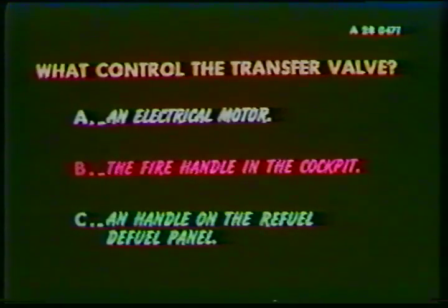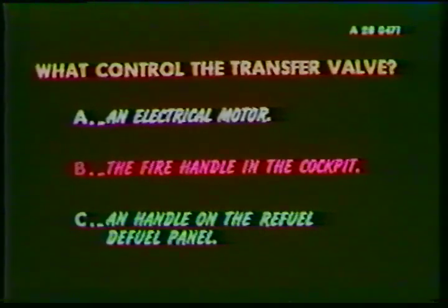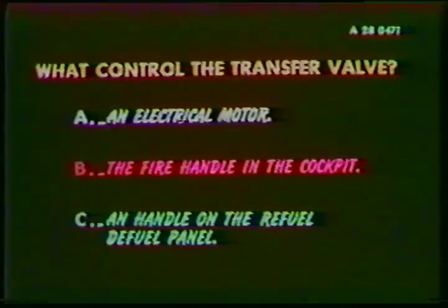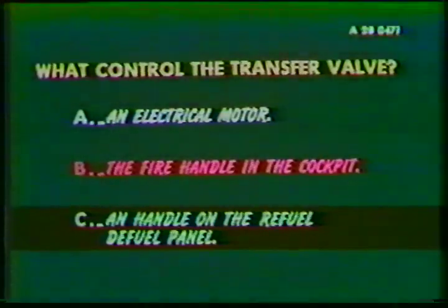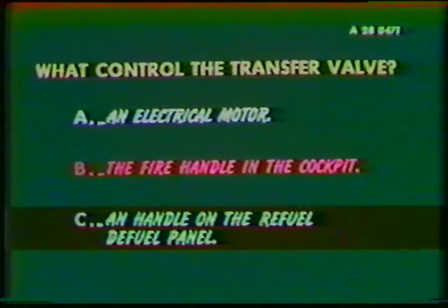Now for the last question. What controls the transfer valve? A, an electric motor. B, the fire handle in the cockpit. C, a handle on the refuel-defuel panel. The right answer is C. The transfer valve is controlled by a handle located on the refuel panel.